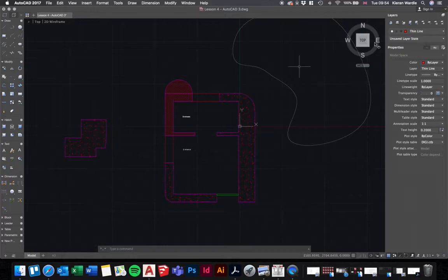And the way that I turn them all back on was I just press the opposite button, which is unisolate layer. So there's isolate layer and unisolate layer. So that's how to create layers. Now the reason that we create layers is so that we can print.